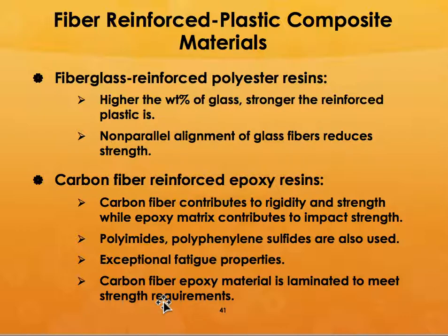In the case of carbon fibers, unless it is absolutely called for, most of the time we try to align the fibers in the specific direction of the loading direction. Because carbon fiber is a rigid fiber composite, it also provides you with very high strength, while the epoxy matrix contributes to the impact strength itself.